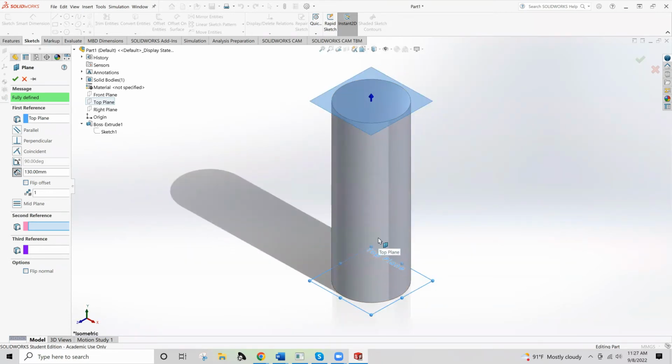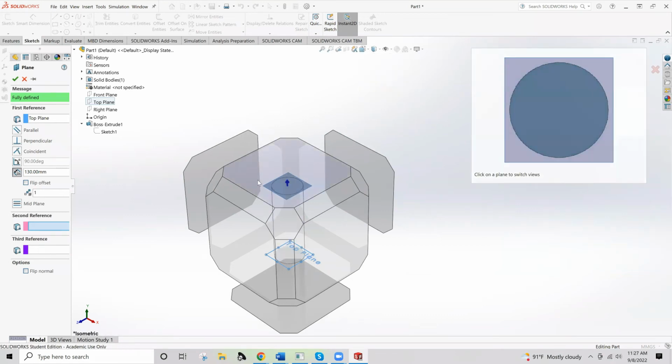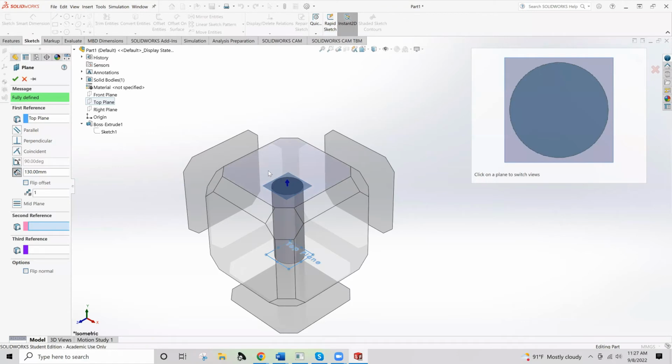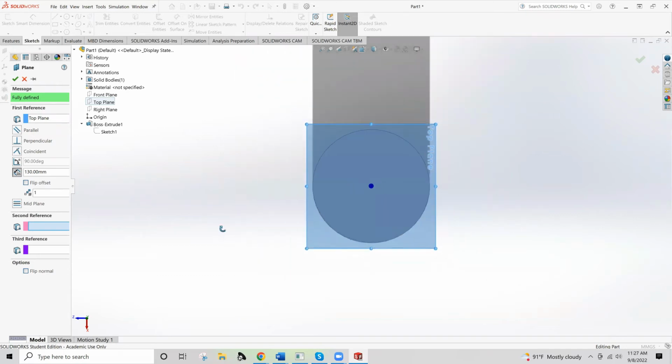A lot of times it goes to this view when you do an operation. The one that I'm going to recommend for the process that we're going to be doing is that you reset your view anytime you're going to be adding a sketch to something. You want to reset your view to be looking straight on at whatever your sketch plane is. There's a whole lot of reasons for that, and I'll demo why right here, for instance.